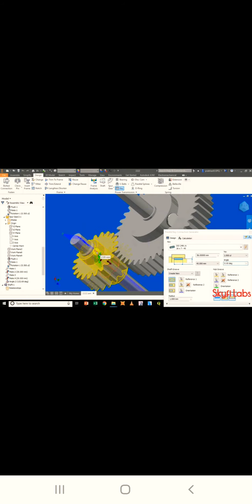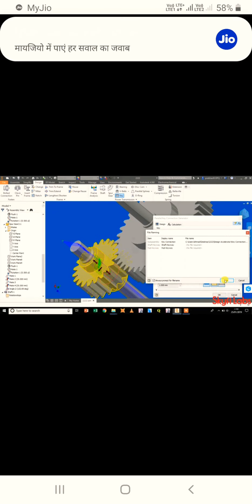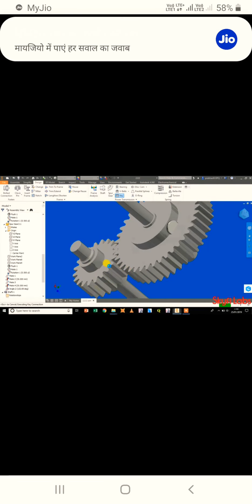the gear. Note that we can also check the design of the key from a failure perspective by using the Calculation tab of the Key Generator dialog box. It will be similar to the design check you had done for the gears earlier.